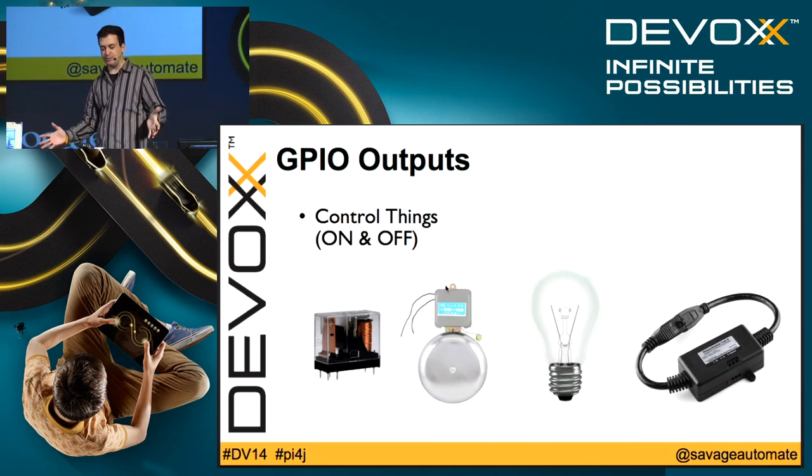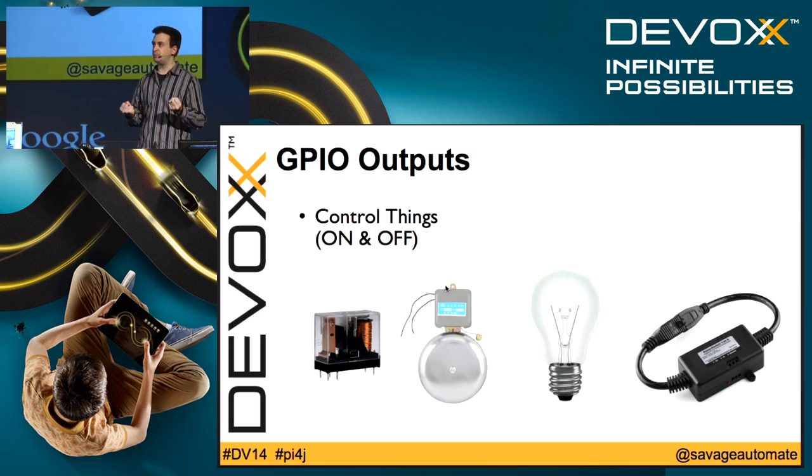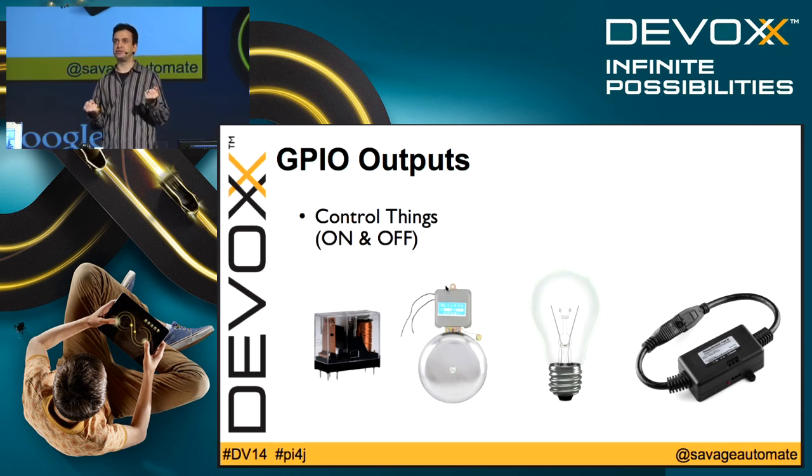So first we're going to talk about GPIO outputs. GPIO outputs are the simplest of the two, and effectively you have this output pin, and you can control or signal it either into a high state or a low state. And we can use that GPIO pin to control things in our world. Control lights, buzzers, motors, things that we want to turn on and off. So GPIO outputs are perfect for that.